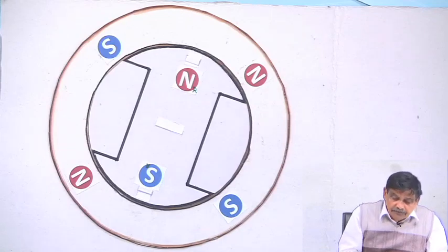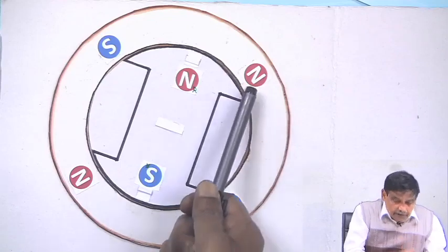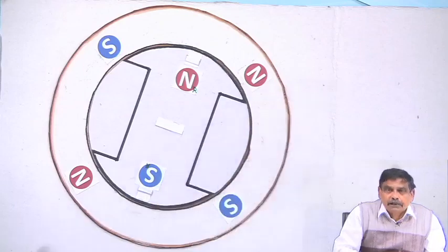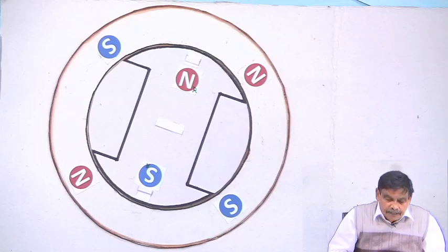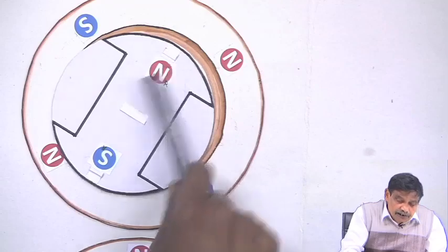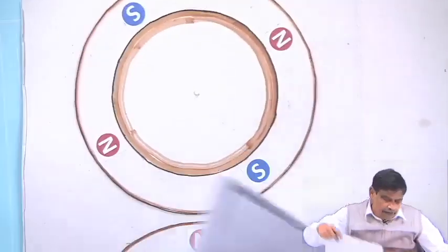It is because someone has thought that any number of poles I produce on the stator, and any number of poles I produce on the rotor, will interact and give me torque, but that is not true. The number of poles produced by the stator and produced by the rotor must be the same. That is why, for example,